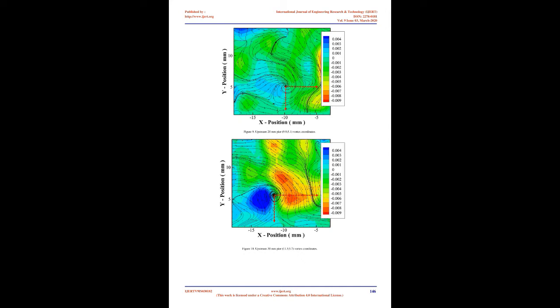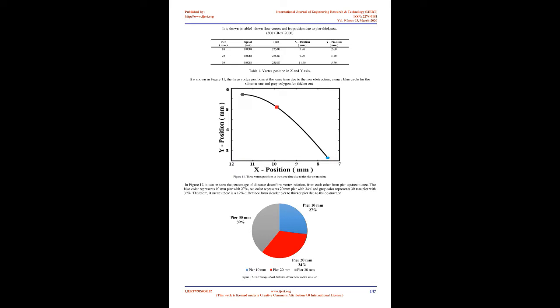For this experiment, a water flow level of 0.09 m was subsequently applied, with particles seeded and illuminated by the laser beam, at a speed of 0.0084 m/s, equivalent to a flow rate of 0.107253 l/s, for the upstream area, observing the downflow position, with a Reynolds number, Re, equal to 235.87. Then it was decided to increase the speed for turbulence appreciation up to 0.117 m/s, equivalent to a flow rate